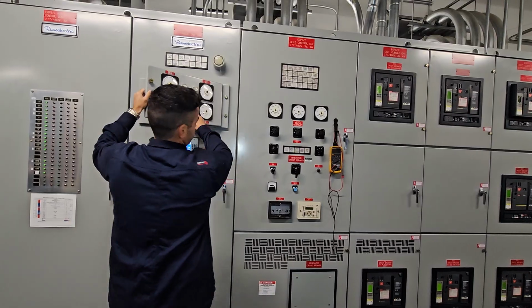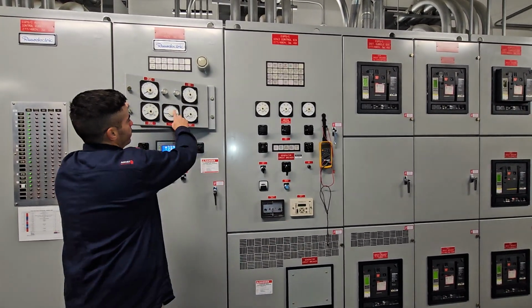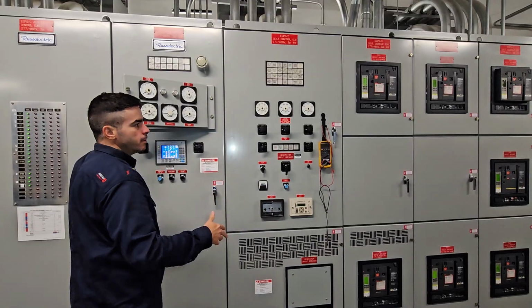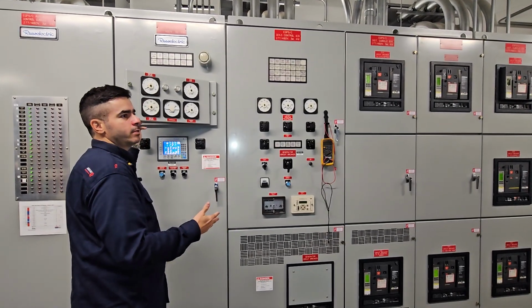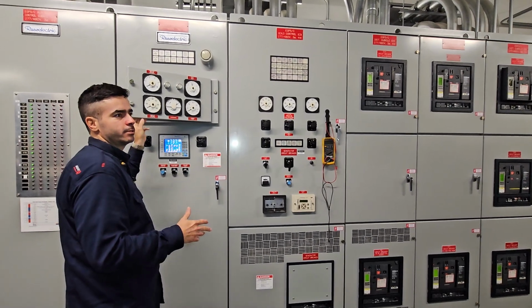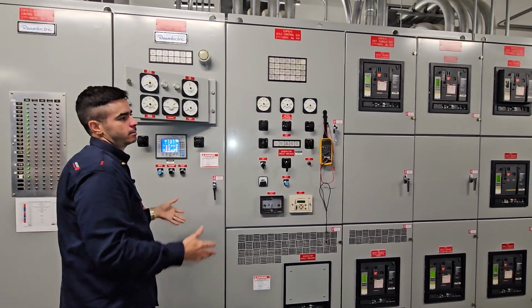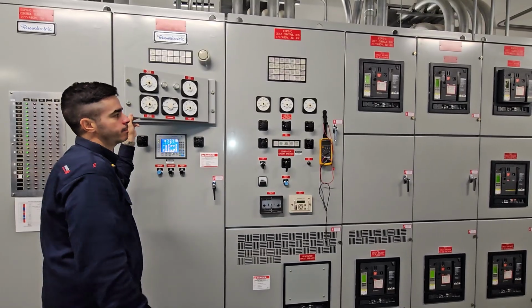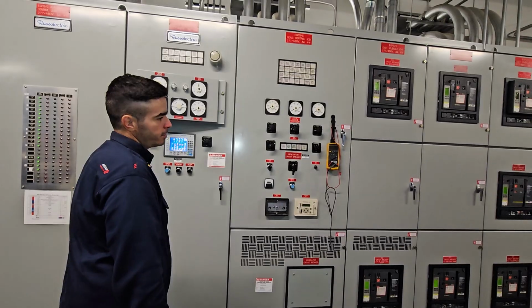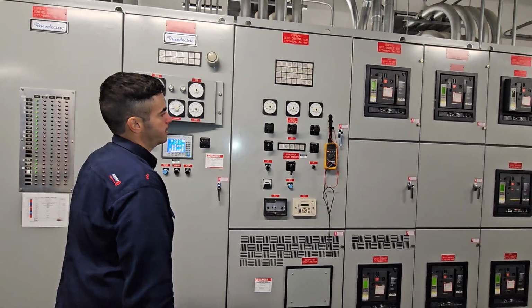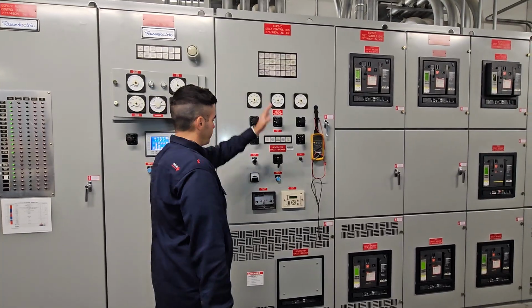And I have to make sure that this is a 12 and then attempt to close, and then the breaker should close. If I do it over here, the system has some relay interlocks that will not allow it to close, but it's not the desired condition. Because if that happens, if this closes like at 6 o'clock, boom, you're gonna have problems, right? You're closing out of phase and it's gonna be really bad. So that's the basics of this.